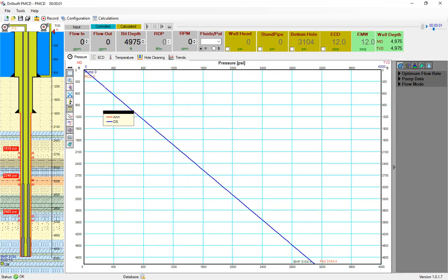On the left-hand side, we've added a PMCD sidebar to control bullheading, determine what kind of light annular mud to pump, to indicate fracture severity factor, allow for flow control to bullhead the gas back into the reservoir, control gas migration rate, gas percentage rate, and to keep track of the total volume of mud or light annular mud bullheaded into the well.